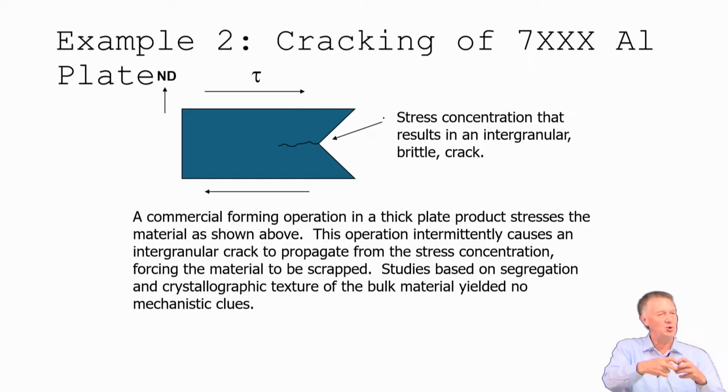The hole is to join the structures, right? So you have to join to the fuselage box, and then you have to join the stringers to the wing spars and those types of things. So you drill holes through this thick plate product to have this huge spar. It's either 5 inches thick or 8 inch thick plate, right?